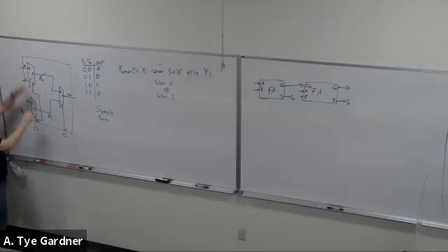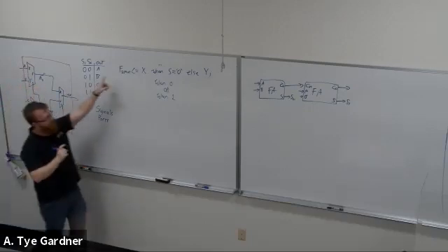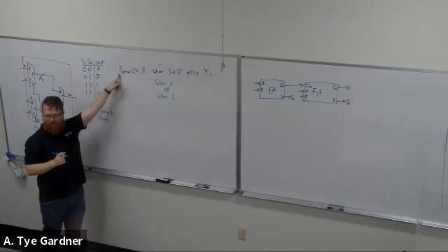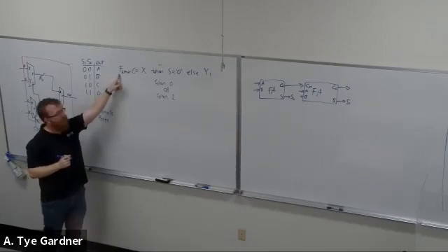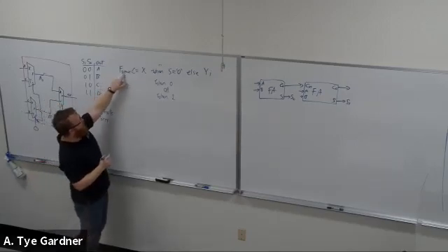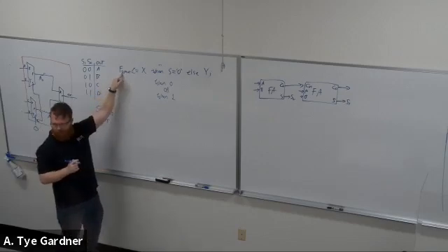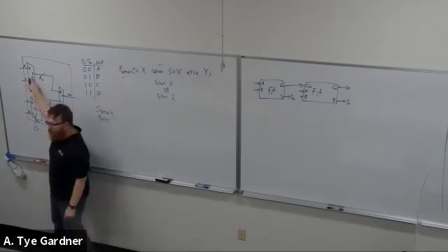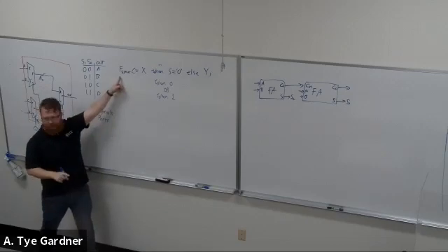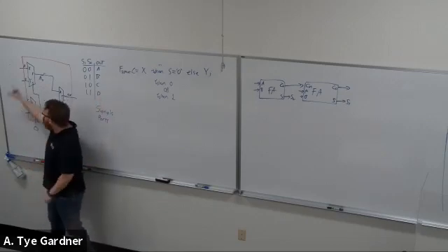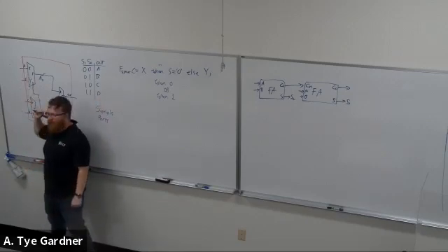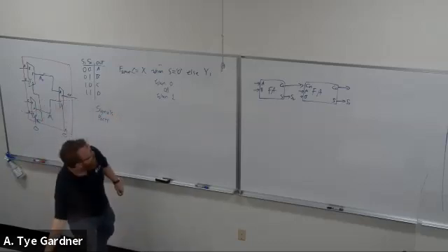So let's focus for now inside of this mux, okay? This is the only line of code that it takes. And I am saying F, I would really just write F, I just want to be a little clear, right? Because the port I named is F. So my port F is getting assigned to X or Y. Okay. That's all this is doing.